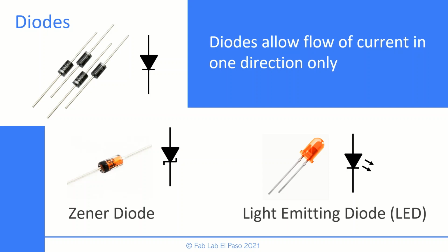The diode allows flow in one direction, but when you have current flowing in the opposite direction, then it doesn't allow it. This is commonly used for protection. When in normal operation, it allows current exiting one component, but if for some circumstance you have reverse voltage from either the user plugging the battery the other way or malfunction of another component, then you prevent damage.